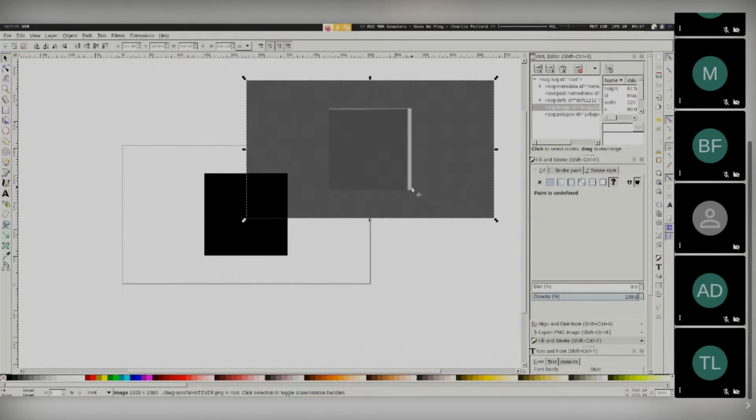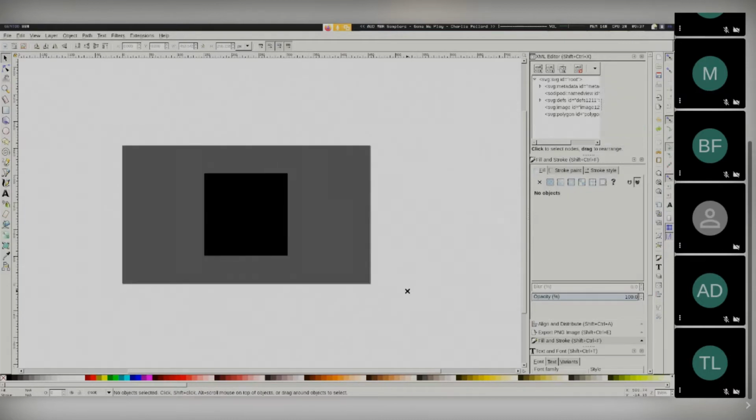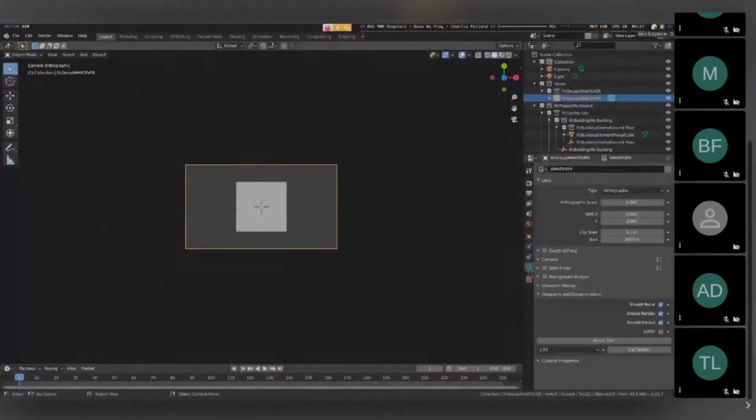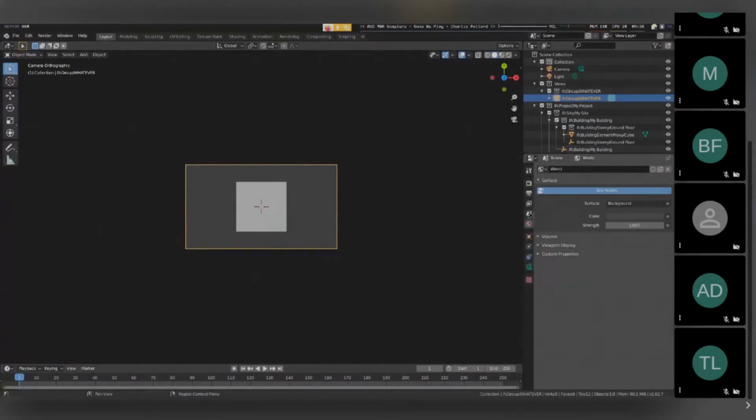And for most scenarios, that's okay, because for most documentation, the bits which you need to be vector, the bits which need to be hatched in and needs to be measured and checked in vector programs are the section cut itself, not the things in the background of the image. Now, this gray background is particularly annoying, but it just uses your default Blender rendering settings. So you just tweak it to whatever you want, and that will change with it.